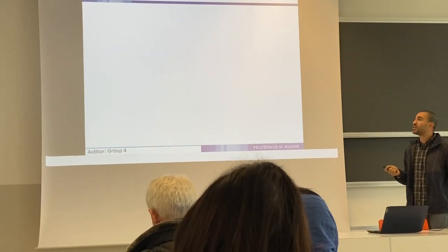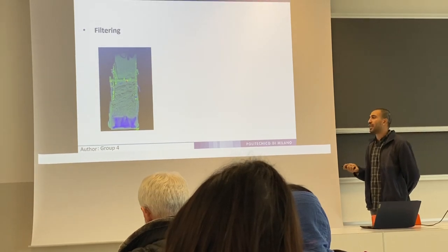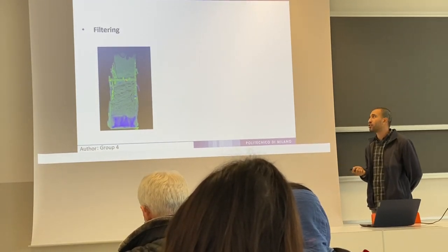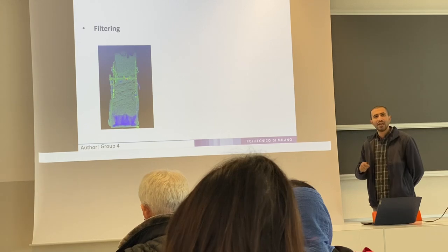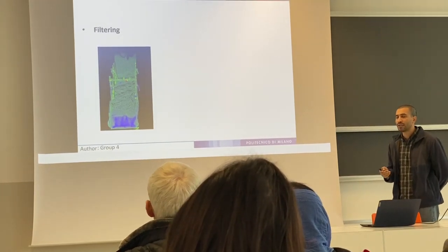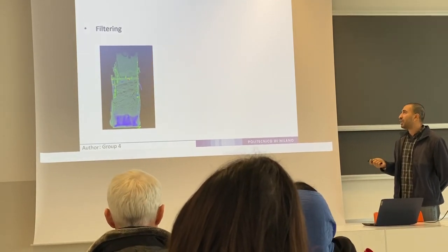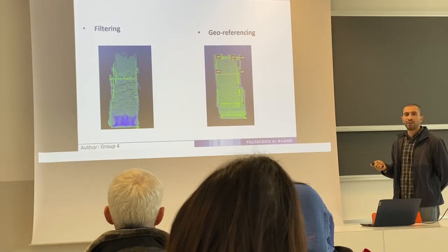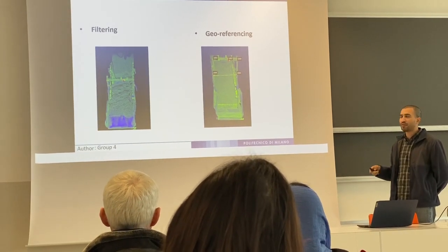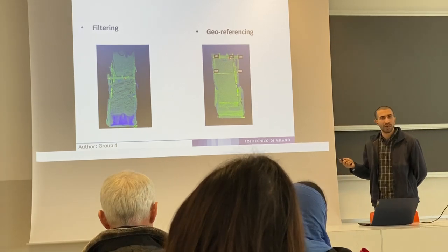For the last part, which is the laser scanner, we wanted to have a dense cloud using the laser scans and to compute the volumetric change. First, we had 3 scans. The first one was very good, the second was very good, the third was distorted by the rainfall, so we only used 2 scans instead of 3. We were lucky in our experiment that our 2 scans were aligned, there was no vertical shifting, so we just needed to geo-reference them using the 5 targets geo-referenced by the total station.